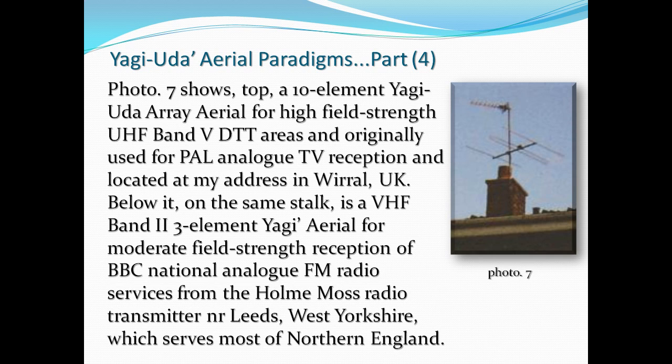At my home on the Wirral Peninsula, I can receive this transmission most of the time perfectly if I switch my hi-fi tuner from its stereo receiving mode to its mono receiving mode. This drastically reduces the background hiss reproduced on my hi-fi system's loudspeakers, because in order to successfully demodulate a monophonic radio transmission, a lower signal-to-noise ratio can be tolerated than is the case with stereophonic reception.